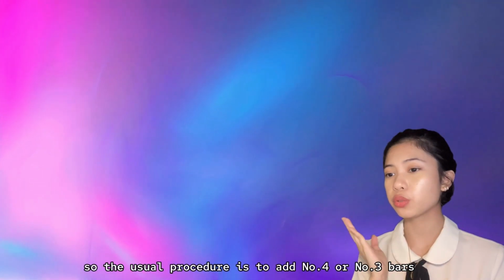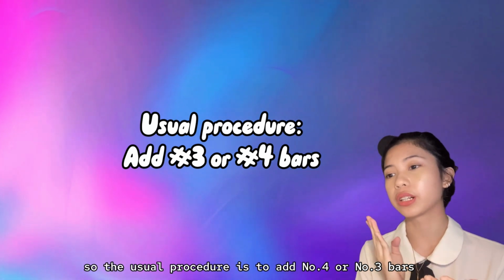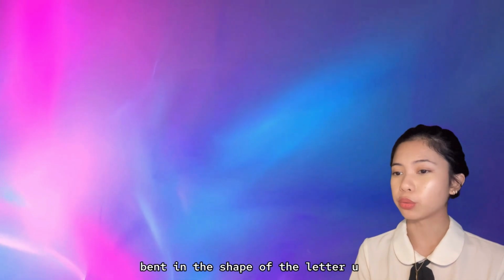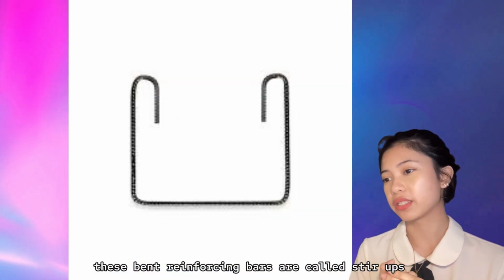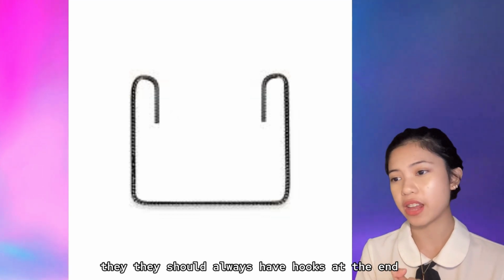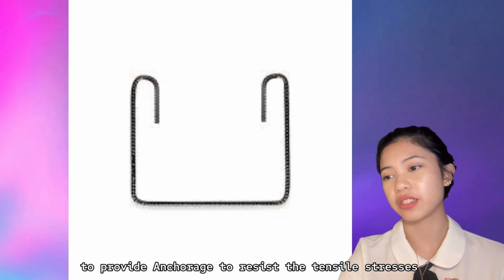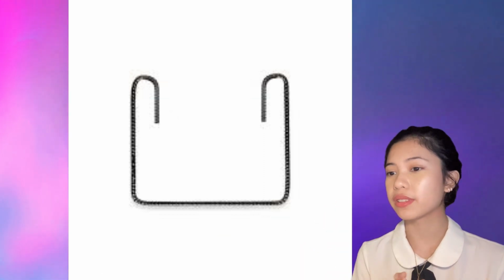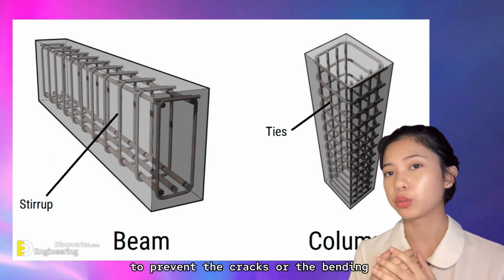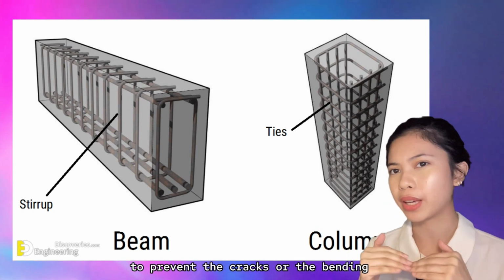The usual procedure is to add number 4 or number 3 bars, bent in the shape of the letter U. These bent reinforcing bars are called stirrups. They should always have hooks at the end to provide anchorage to resist the tensile stresses. So stirrups yung usual procedure to prevent the cracks or the bending.